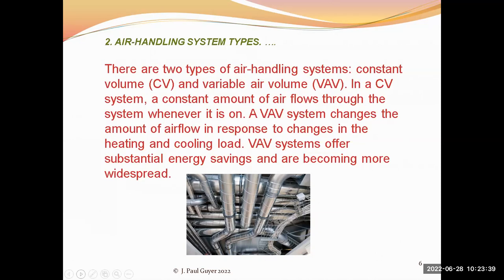And so each discharge point for the air into the different occupied spaces has a control box, and it has a thermostat. So there's a bunch of thermostats all over the place, and they're opening and closing these VAV boxes, variable air volume boxes. And this provides substantial improvement in occupant happiness, because they can have the thermostat set however they want it in their space.